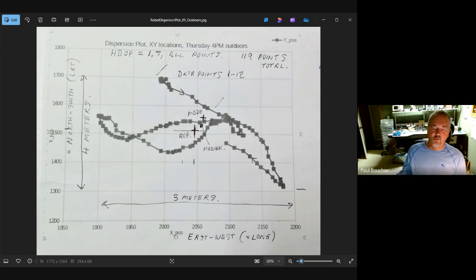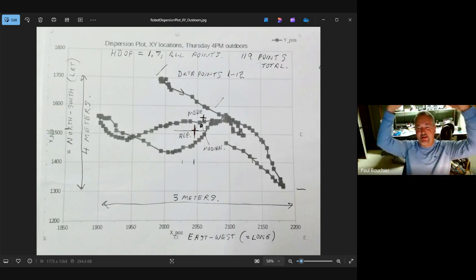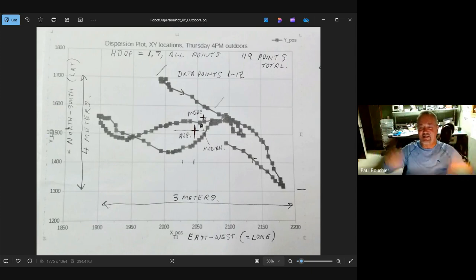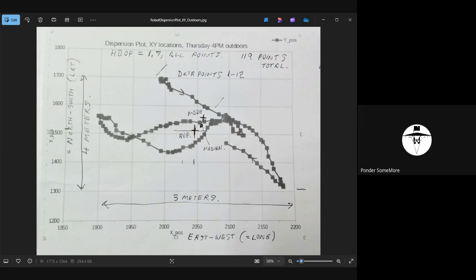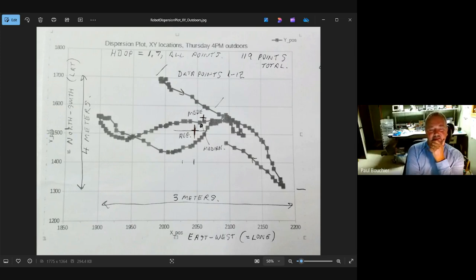What would be really good would be to ground truth this with an RTK reading. That would be interesting, while the robot is in motion. My understanding of what causes this wandering is that the troposphere or the ionosphere is moving around, and its propagation delay changes because the signal path wanders around, but it does so because it's up in the atmosphere where things don't move tremendously quickly. Yeah, that's right. And so the fact that it wanders in a serial manner, step-by-step following a path, is not surprising.